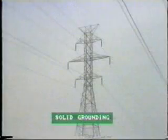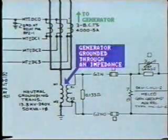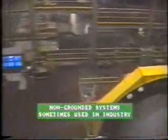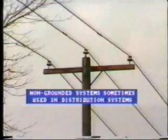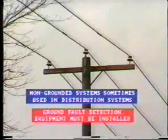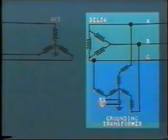Now, at this point, let's briefly summarize the methods of grounding which you will encounter. Solid grounding. This is the case with most utility systems above 40 kV. Generators may be grounded through an impedance so as to limit the magnitude of fault current. Non-grounded systems are sometimes used in industry where a continuous power supply is required. Distribution systems are sometimes not grounded, and in this case, ground fault detection equipment must be installed. Delta systems can be grounded with grounding transformers.